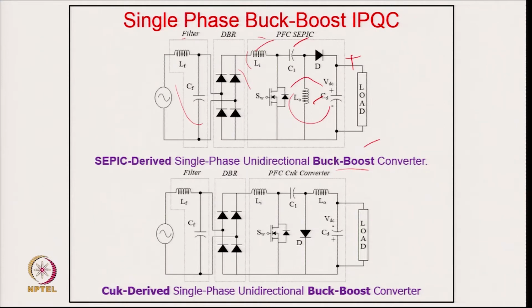If we talk about DCM for inherent power factor correction, we normally prefer the output inductor current to be discontinuous. The reason is that if you take the input inductor discontinuous, the size of the EMI filter will increase. But if you take the voltage across the capacitor discontinuous, then the voltage stress across the device and diode increases substantially, very high, so you have to select a quite high voltage rating. So these are the relative merits and demerits of these designs.